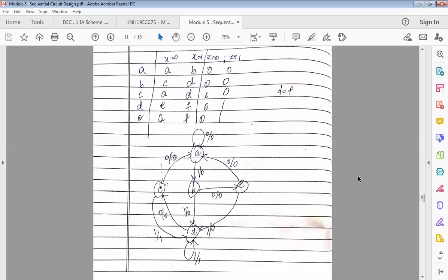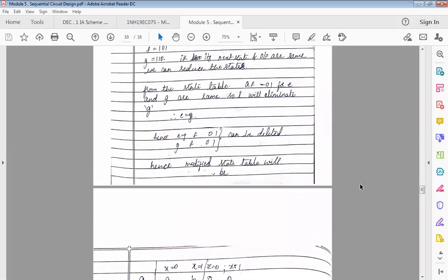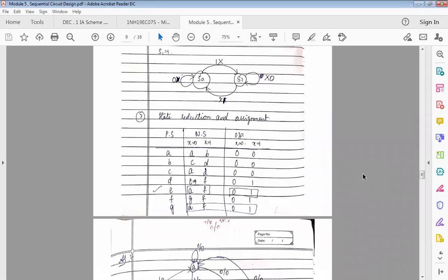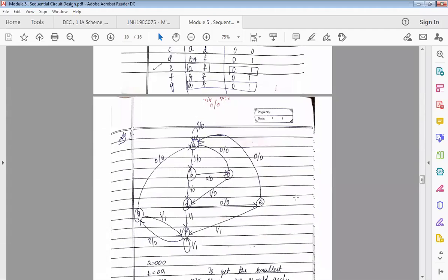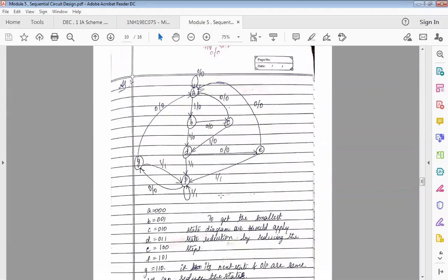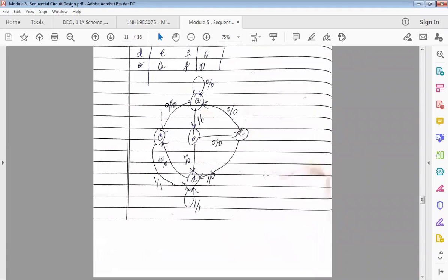Okay, so now I think you all have understood the importance of reducing the state. Sometimes there can be a question on this, but many times these kinds of complex scenarios wouldn't be asked. But I wanted to discuss this complex situation wherein it helps you analyze different things. This is a complex case which I've taken, where there are three kinds of substitutions happening. First, I try to compare, that is one kind of substitution. Then I make E equal to G. Then here again I make it G. And again I compare this with here. So one more state I reduce. This one after the other, step by step comparison happens, and this huge state graph is actually reduced to a smaller state graph.